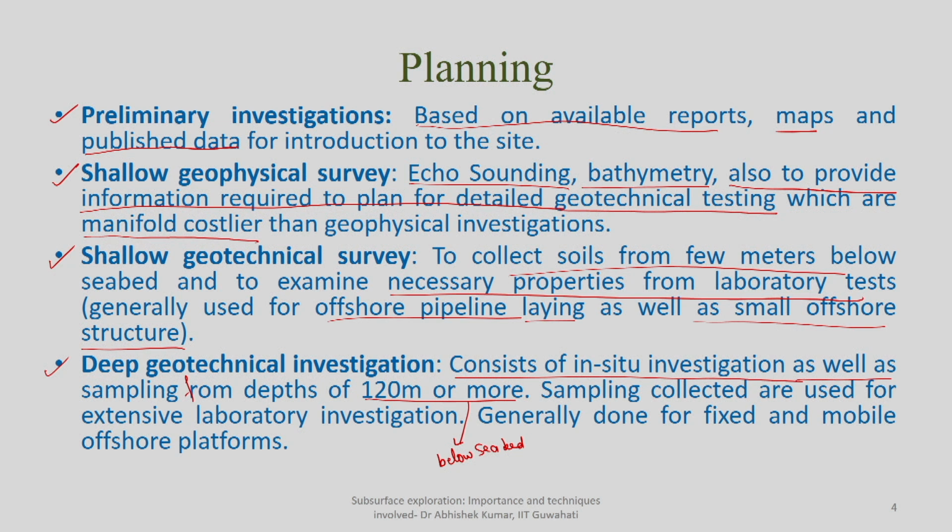Again, for design of anchor for these kinds of things, or particularly when these are not floating rigs, rather it is fixed or directly supported on the seabed, you have to go for this kind of depth. So, samples collected from deep geotechnical investigations are used for extensive laboratory investigations, which are again done offshore itself, and are generally done for fixed and mobile platforms.